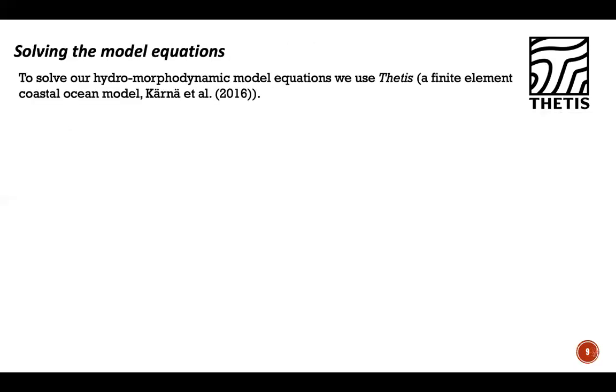So as I promised, talking a little bit about the model and the equations. The hydrodynamic part of our model is the shallow water equations, because our model is two-dimensional. And the morphodynamic model is made up of two equations. One is a simple bed level change equation, and the other is a sediment equation, which is just an advection diffusion equation where you're conserving sediment.